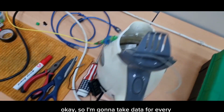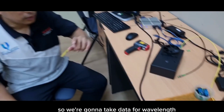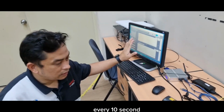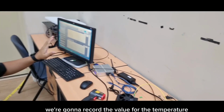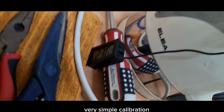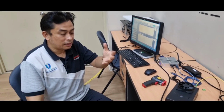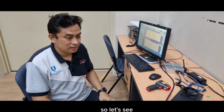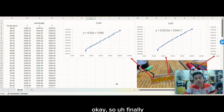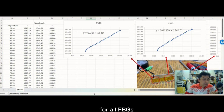We're going to take wavelength data every 10 seconds. At the same time, we're going to take the value for the temperature using the temperature sensor. So this is a simple calibration. We're going to calibrate the values from room temperature until 100 degrees. Finally, we plot the results for the temperature versus the wavelength for all FBGs.